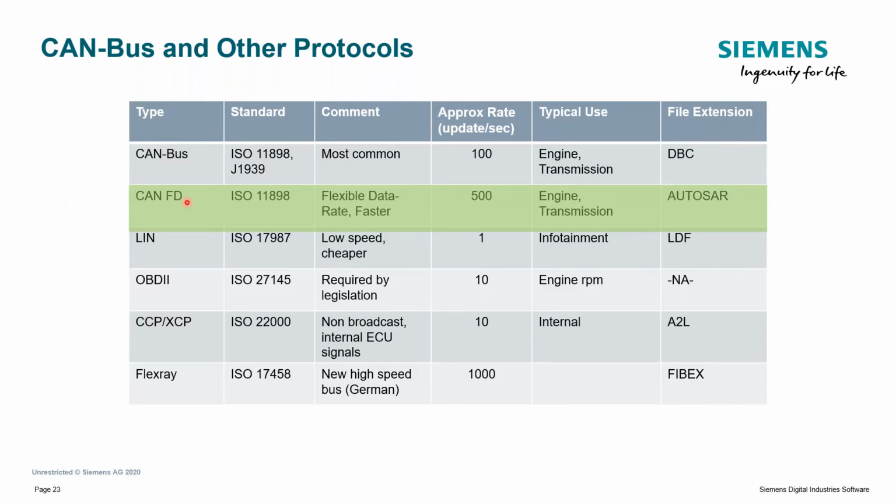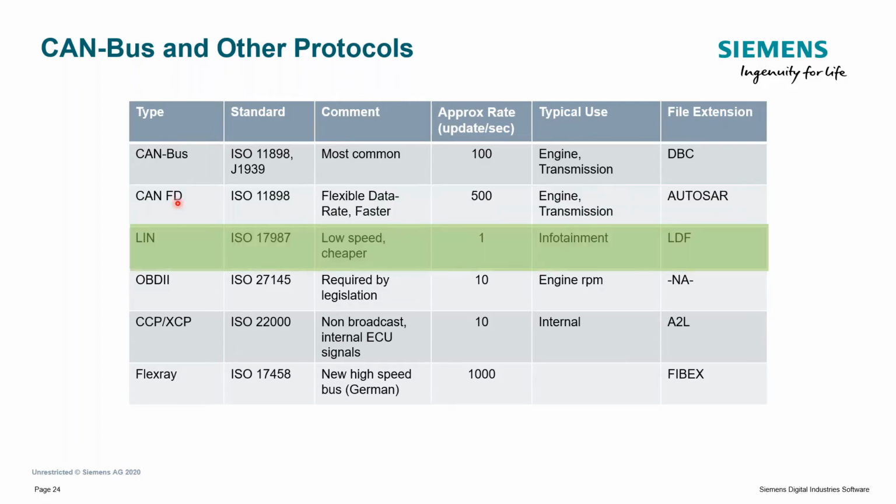So on the SCADAS units, you can upgrade to a CAN FD interface, which handles both CAN FD and CAN bus. The original hardware was CAN bus only. Now you can get a CAN FD plus CAN bus compatible. Different files are required, files for a higher rate. Pretty common now. Many vehicle manufacturers are switching from CAN bus to CAN FD.